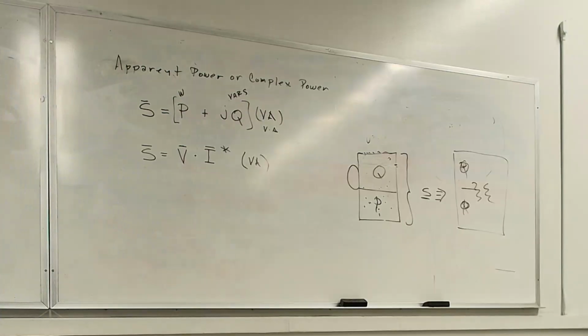If you want your transformer to be as efficient as possible, you want more P than Q. You want to minimize the amount of Q that the transformer transfers from one side to the other. By the way, the transformer itself absorbs vars. So it not only transfers vars from one side of the transformer to the other, but it also is itself a big inductor and consumes vars.